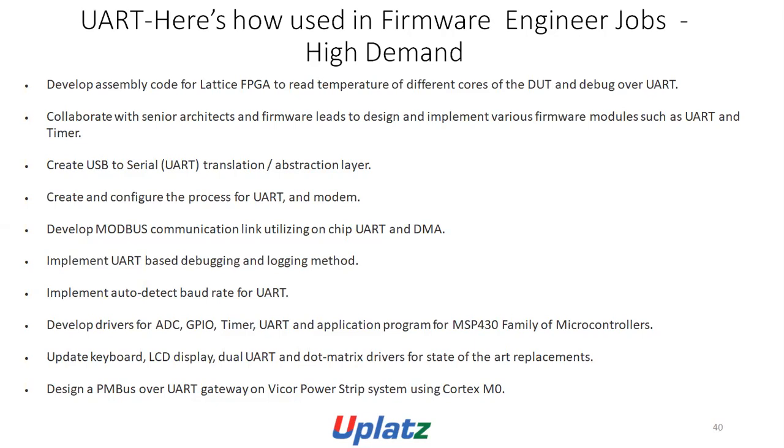Create and configure the process for UART and modem, develop Modbus communication link utilizing on-chip UART and DMA, implement UART-based debugging and logging method, implement auto-detect baud rate for UART, develop drivers for ADC, GPIO, timer, UART, and application programs for MSP430 family of microcontrollers from TI, update keyboard, LCD display, dual UART, and dot matrix drivers for state-of-the-art replacements, design a PMBus over UART gateway on power step system using Cortex M0 ARM processor.